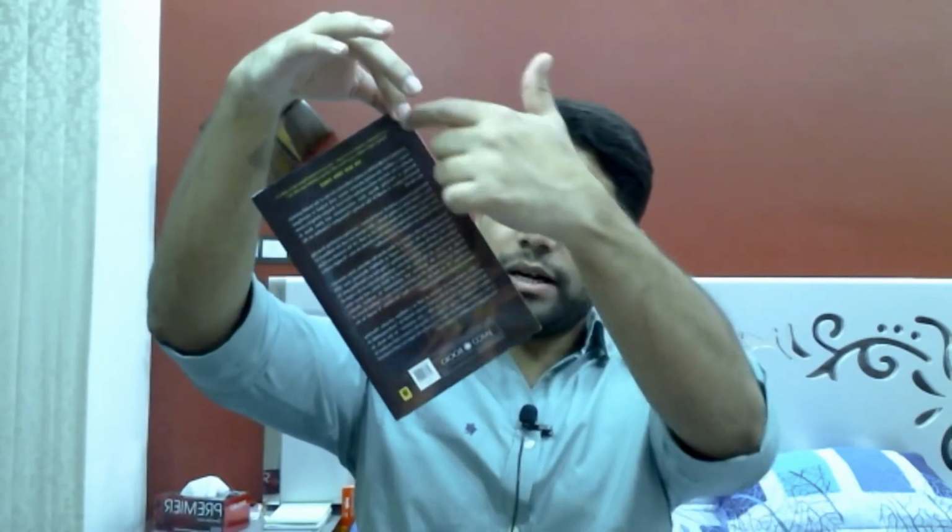In order to find the center of gravity experimentally, you can hang this plate at some point. Now your plate will always be aligned in this vertical direction, along the center of gravity axis. So you will mark a line like this.